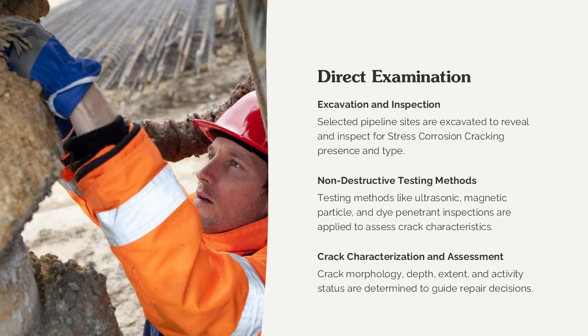Direct examination is the step where selected pipeline locations are excavated to confirm the presence, type, and severity of SCC. This process includes coating removal, visual inspection, and the application of appropriate non-destructive testing methods such as ultrasonic testing, magnetic particle inspection, or dye-penetrant testing. The objective is to characterize crack morphology, depth, and extent, and to determine whether cracks are active or dormant.